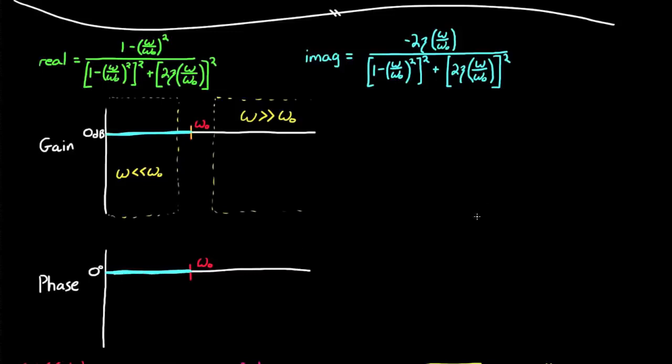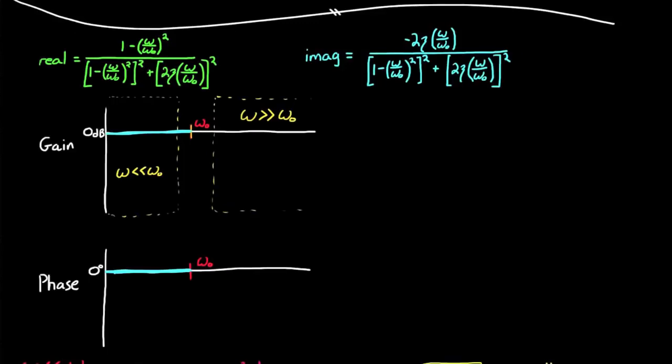I know you might be thinking that this is only accurate when the input frequency is much lower than the break frequency and not up to the break frequency like I've just drawn. But remember that this is a straight line approximation only, and it's intended to give you a rough idea of the shape of the plot and not give you exact values.